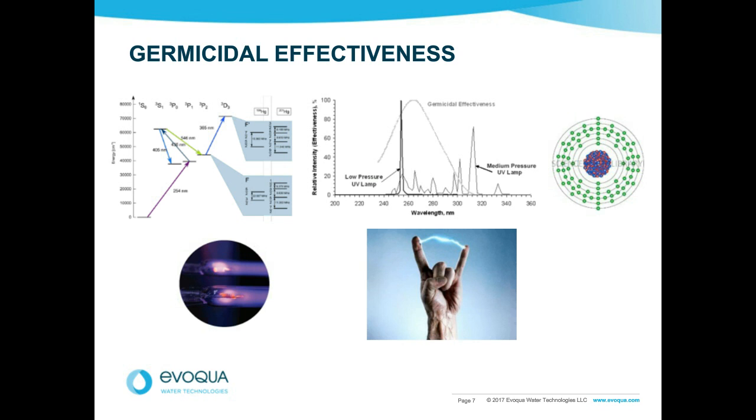You can't take an ordinary UV system and expect it to be an effective dechlorinating agent. You need to properly size it for that specific application. It's a very high dose, and the machines are bigger than disinfection machines. They look slightly different, but again, when properly sized, yes, it's a good application.